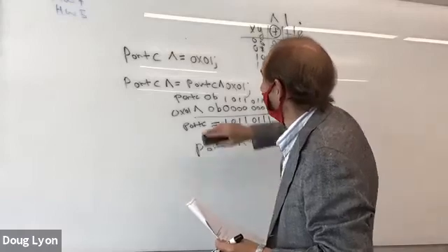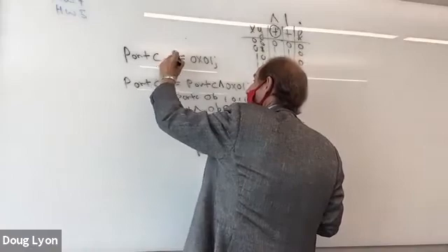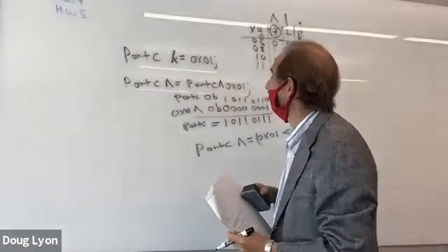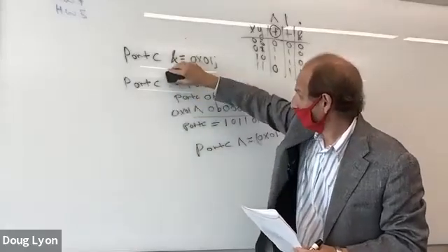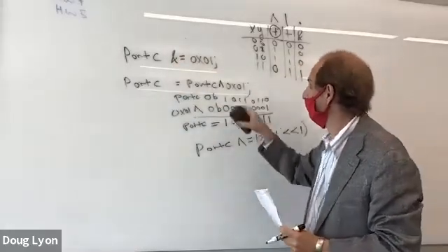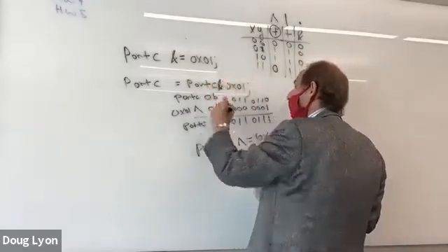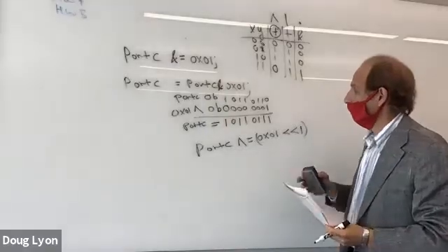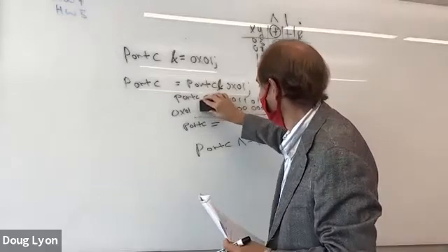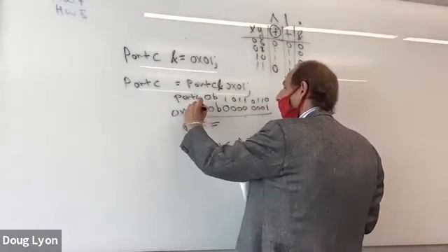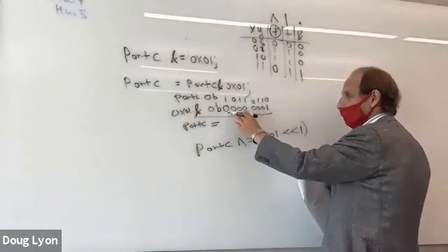And we say, what does this do? We put the ampersand in there. What does it do? Well, it does the same thing as this. It says port C is equal to port C AND 0x01. So what will the output be if the operation is AND? The answer is, whatever this is over here, it's all zeros.